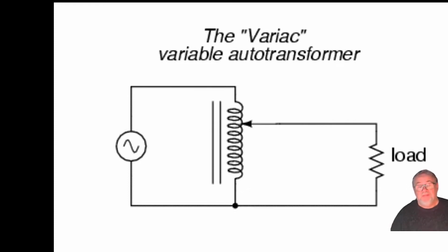If you're using it for that purpose, then you want the Variac to have a low rated fuse in it, so that if your equipment suddenly starts drawing a lot of current, the fuse pops. But when you switch the Variac on, it's a great big coil of copper wire straight across the mains, so it will blow the fuse.